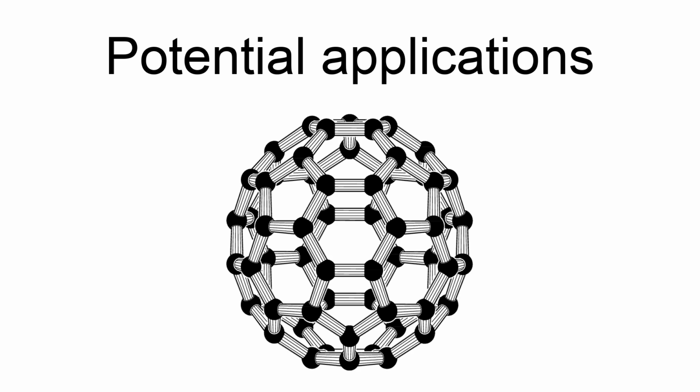Bonds to carbon nanotubes require their carbon to change from near-planar sp2 bonding to tetrahedral sp3 bonding, thus disrupting their tubular geometry and possibly weakening them. Nanothreads may be less susceptible to loss of strength through defects than carbon nanotubes.